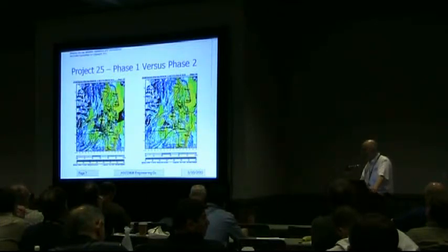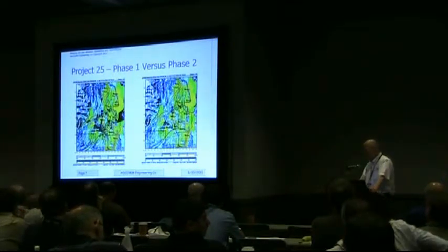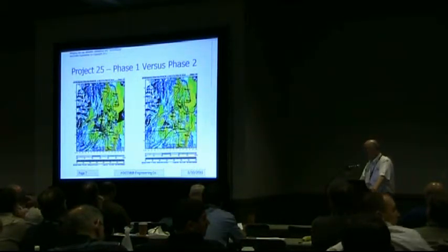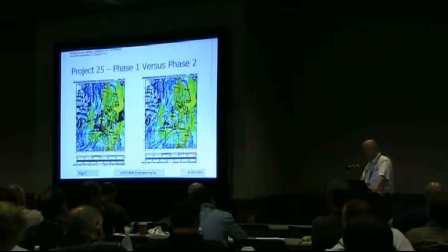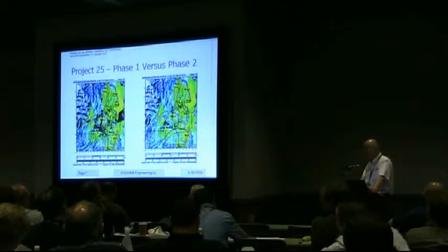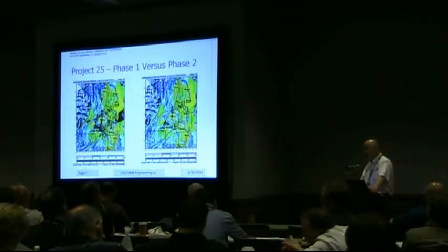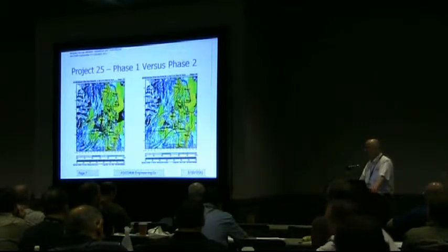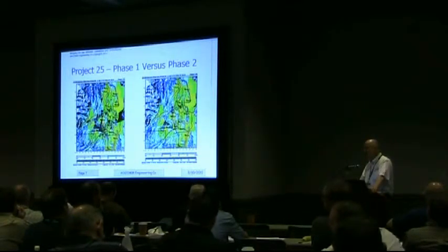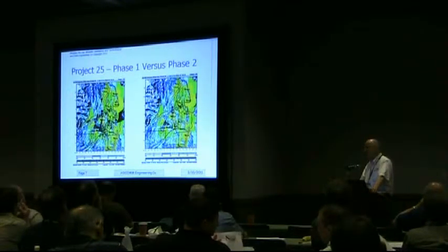The numbers that we've gotten back, at least unofficially, for delay tolerance is that on phase 2, you can do up to about 80 microseconds. But you are right, one of the issues is that you still have 9.6. You still have a phase 1 control channel, right? So that's one of the gotchas about doing a phase 2 system.